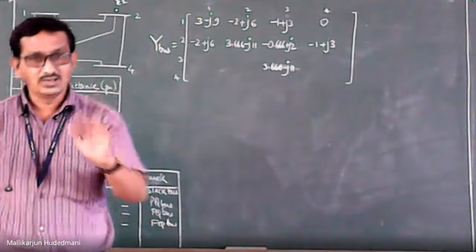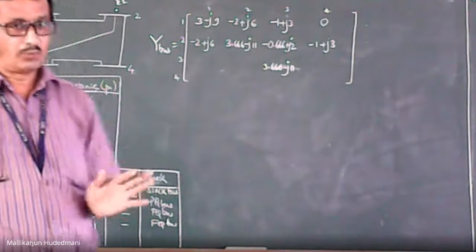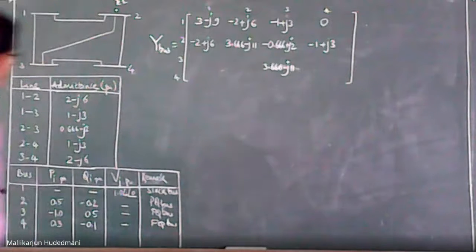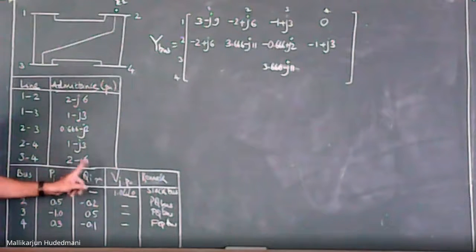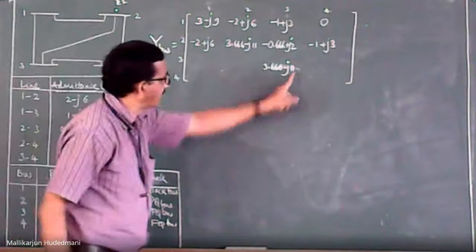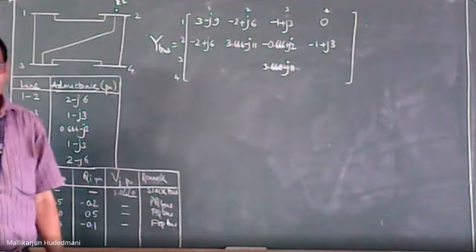Will not worry. Are they same or not? It is not our problem. Okay. So at bus 3, 1.66 and we have 2. It becomes 3.66 and 3 plus 2, 5, 5 plus 6, 11. So it is minus J11. This is called diagonal value at bus 3.